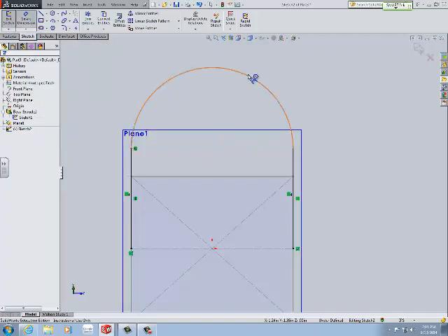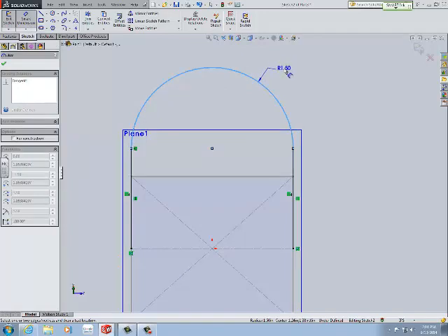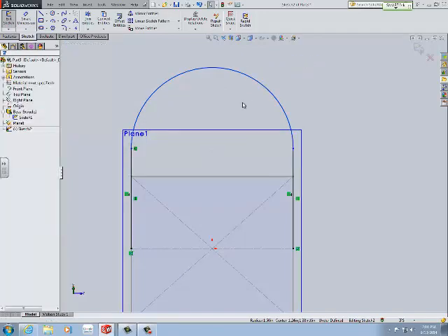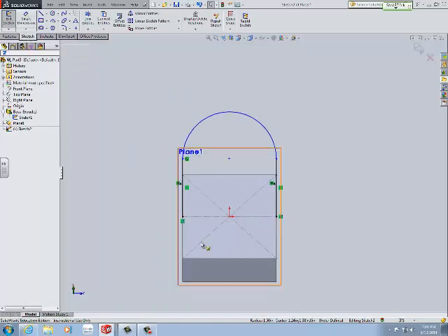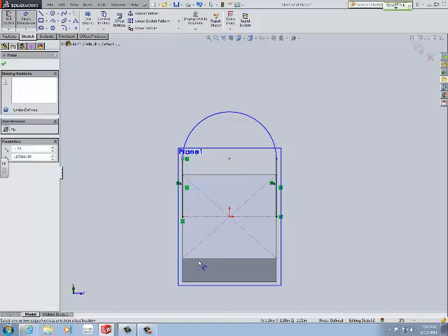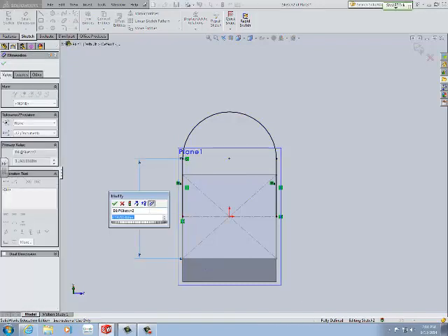And now we're going to do the extrude. Radius 1.5. Notice that we are on top of the surface. So what we will need to do is extrude a different height here and a different height overall below. What we could have done instead was add another plane, but we wouldn't want to do that because that's extra work that is not necessary. So instead, we're going to go to Features, Extrude Boss Base, and select the sketch that we just did.